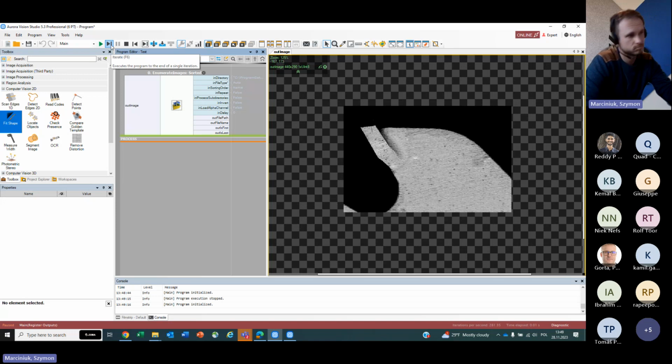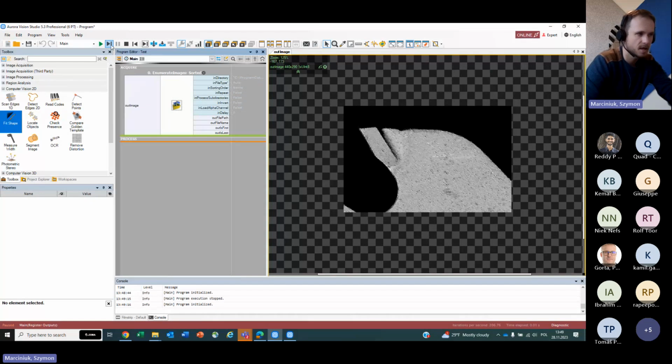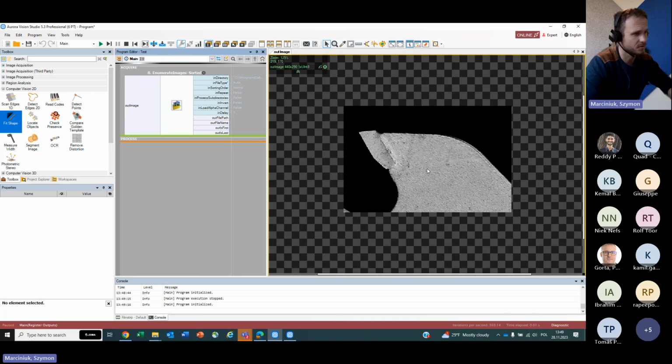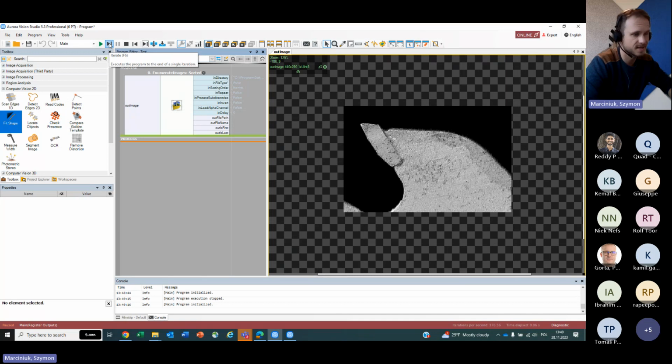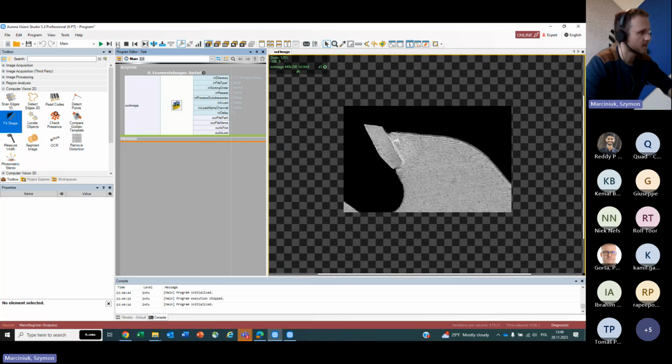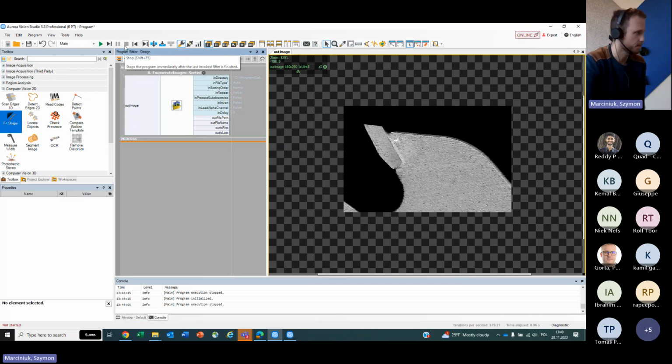And the most typical choice for such a localization, for such a fixturing, would be pattern matching. That's the most typical tool to locate object in a field of view. But in this case, it will be difficult because there is no fixed shape in our image that we could use as a template. Everything is a little bit shaky here. That's why we will stick to edge detection tools, to shape fitting tools, and we will do just fine using them.